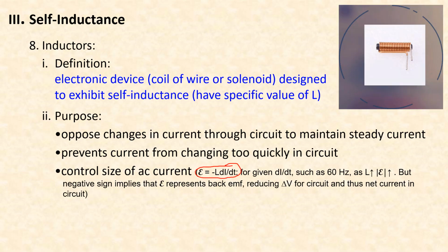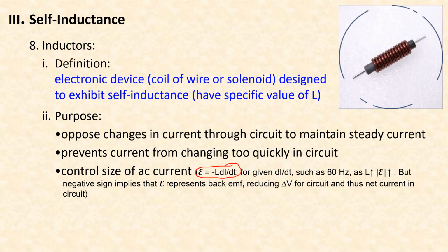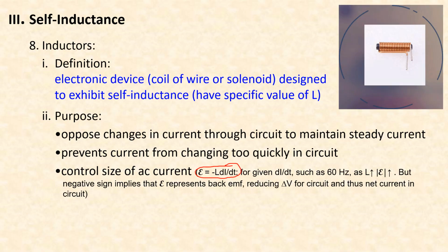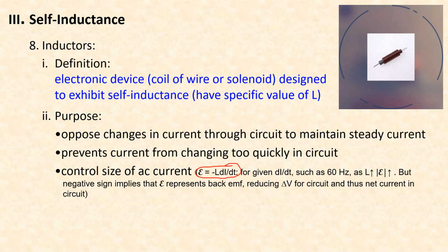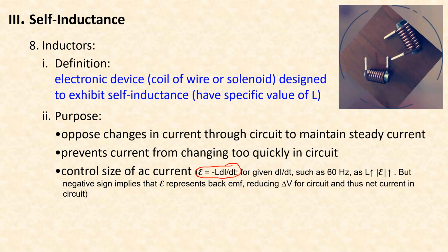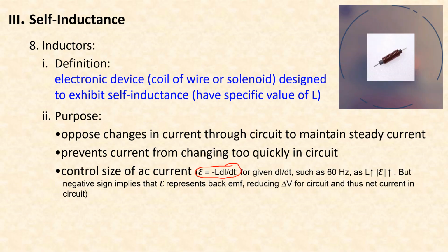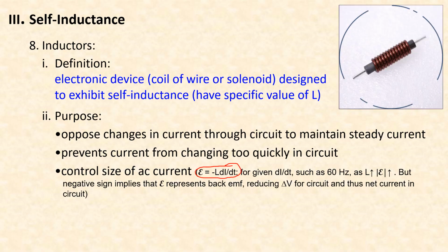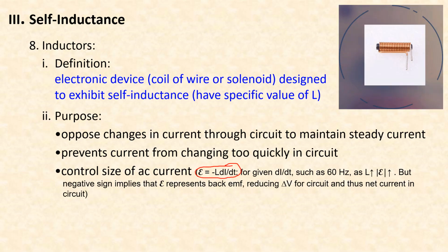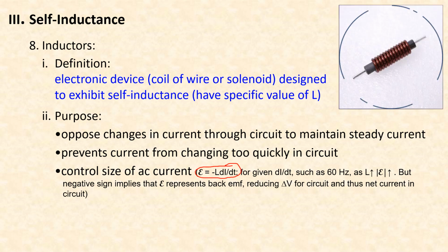So to look at this from a slightly different perspective, let's revisit a previous discussion that we had involving electromagnetic induction, where we looked at the case of motor overload. When the armature of a motor gets restricted from turning, the end result is that too much current exists in the motor's windings that may cause too much thermal energy to be produced and perhaps melt the circuit insulation.